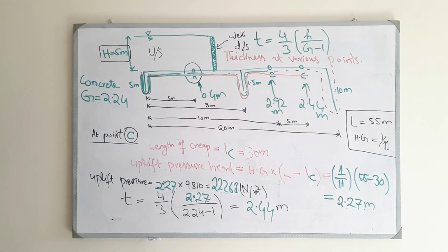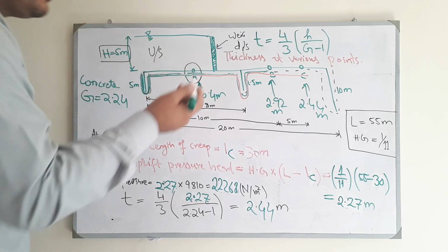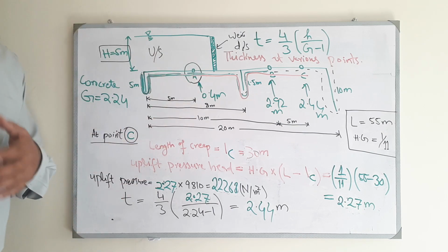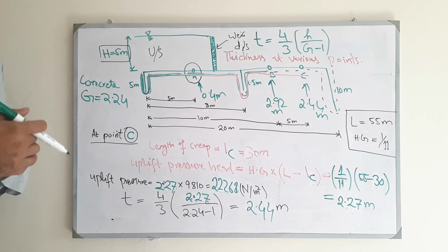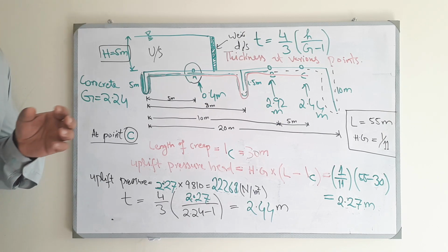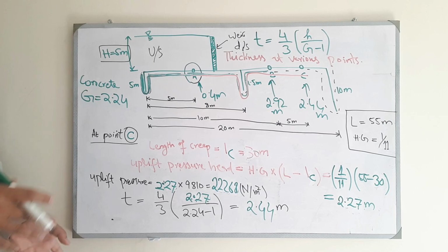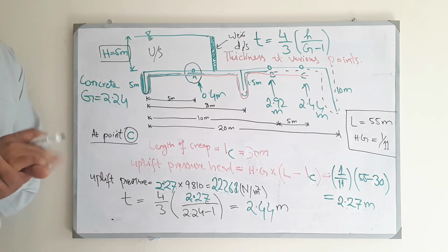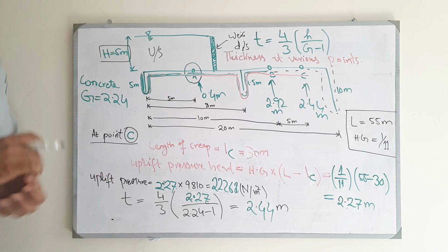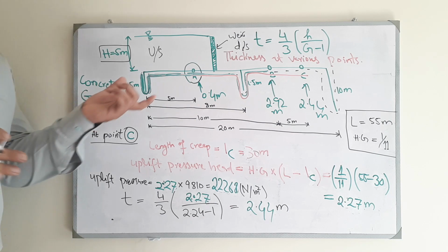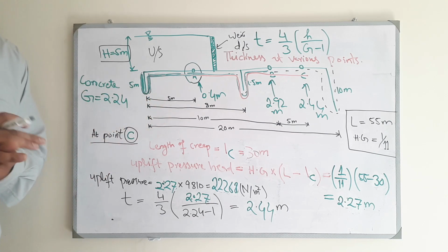He also didn't provide any corrections due to floor thicknesses. So then the Khosla theory has provided these upgrades to the Bligh's theory. Now still there are some limitations, but still most of the small hydraulic structures the impervious floors are being designed in the subcontinent by the Bligh's theory, and if there are larger structures, then we normally move to the Khosla's theory.